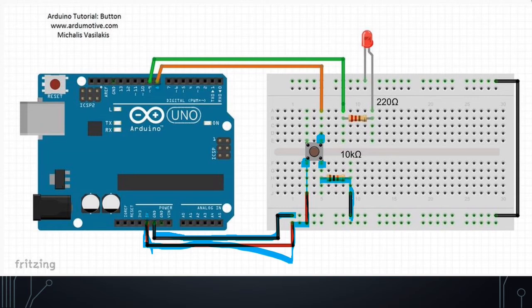So we have our push button connected like normal, and then we're just going to connect an LED like we normally would. And so the shorter leg is grounded. Remember, shorter, negative, and so that's the one that's going to be grounded. So here, ideally, you put a little wire, kind of like we did on the resistor over here, in between the little pins, the row of pins, and the ground. But here they've just directly connected the LED to the ground, which is fine, but not preferable.